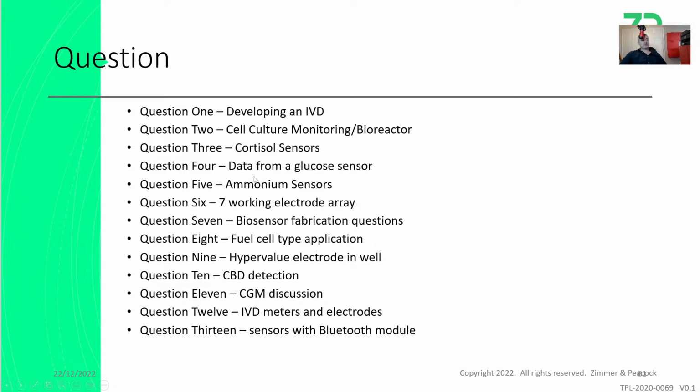Data from glucose sensing: your data makes sense in the way that you're doing the sensing. A couple of things. Watch that video featuring Andre, and also you have to be testing in the clinical range. I must admit that Easy Flex board that you're using, we've always tested it in the 0 to 20 millimolar range. You're going, I think almost 0.2 millimolar, at least an order of magnitude less. So I'm a little bit hesitant on that particular board, not on the sensor, by the way. Sensor I have no problems with.